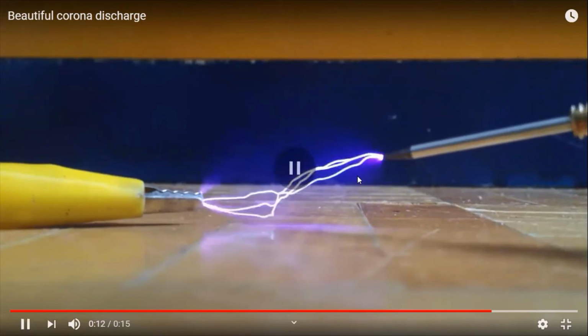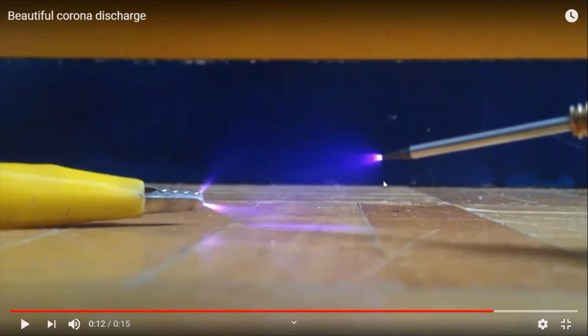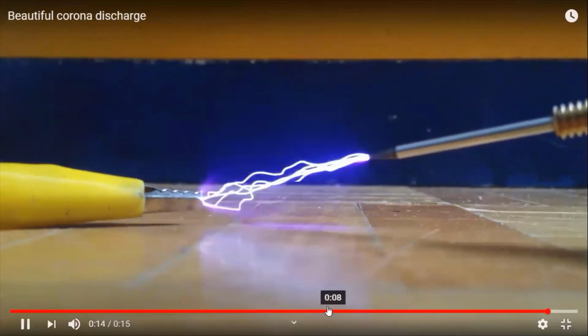Okay, so this is going to form like a cloud of ions here. This is the coronal discharge. And of course, when you get closer, it's like lightning, right? So you're forming this direct current again. But in industry, we want to form this coronal discharge. We want to form the ionized gas molecules. We want the blue things here. We don't want it to form this direct current. This is the state when we're trying to form the coronal discharge.